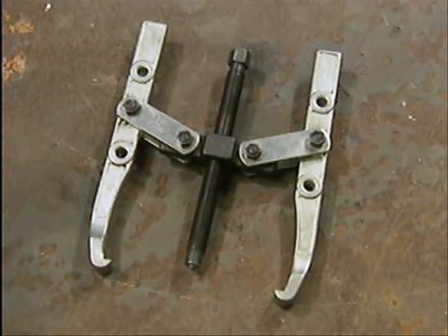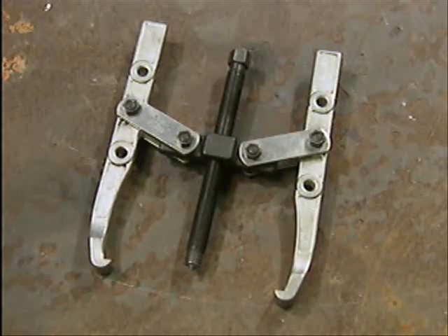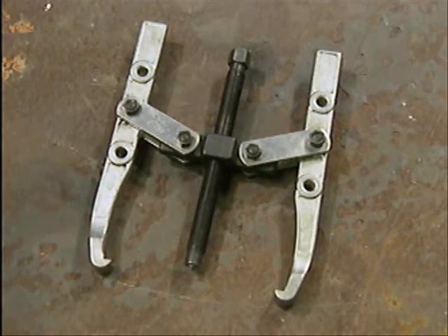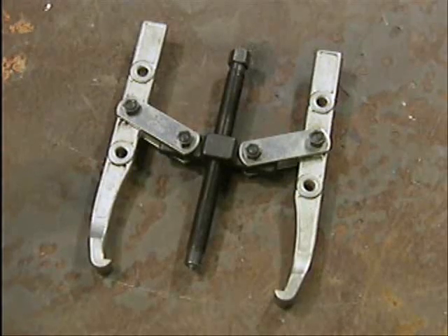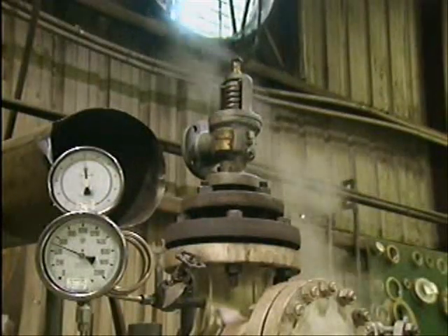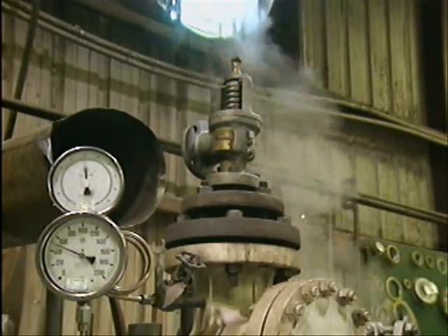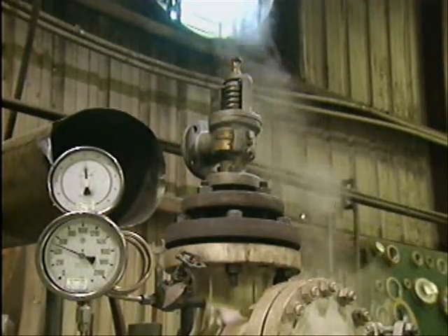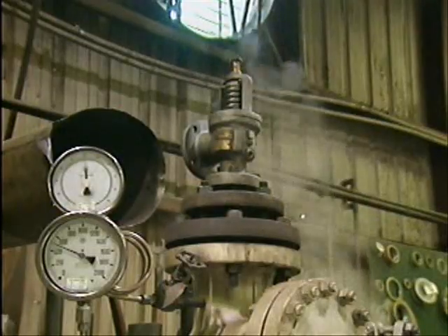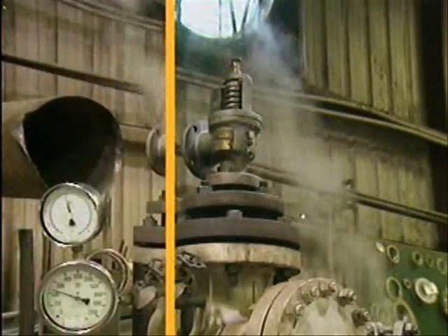Next, prepare to perform the necessary tests. An important preparation for many testing procedures is gagging the valve. Gagging involves installing a device called a gag that keeps the safety valve from opening during testing. We'll look at a typical procedure for installing a gag on a 2-ring Huddling chamber safety valve. The valve's release lever and the protective cap have been removed so the top of the valve stem is exposed.